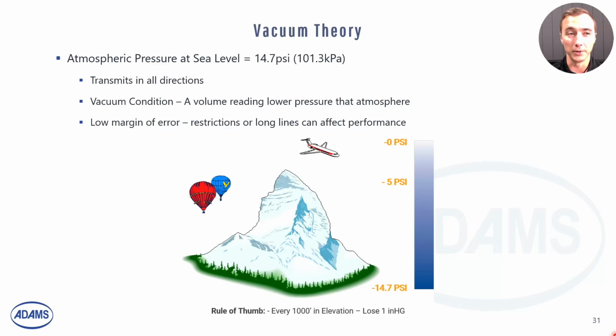People are often familiar with the terms PSI gauge or PSIG, and also PSI absolute or PSIA. So that's where that's coming into play. Many of the gauges that we use on a day-to-day basis are working off of PSIG, so they already account for that 14.7 psi that's present at atmospheric pressure, and that's the theory that vacuum systems use in material handling.